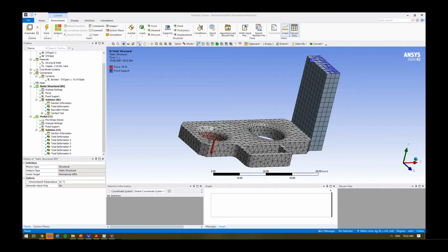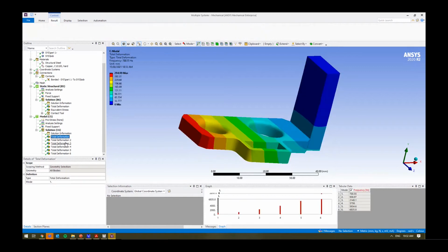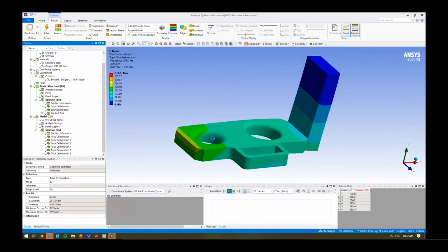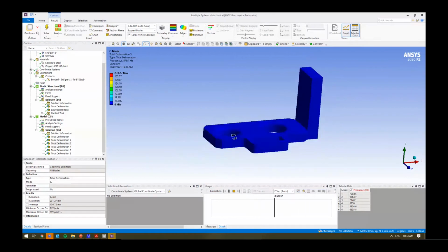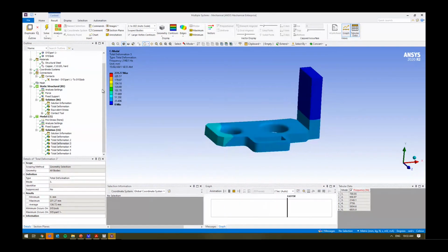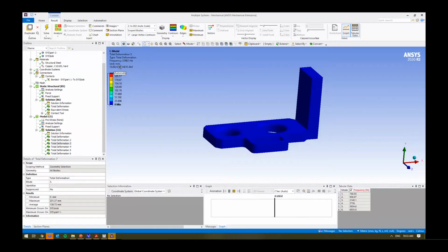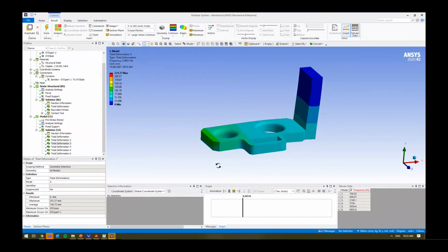Absolute or relative to each other, Prasad, I'm not too sure there. The mode shapes will just show you what the deflection is, what the shape is, but you should never use the mode shapes as an actual value, right? These values don't actually make any sense.